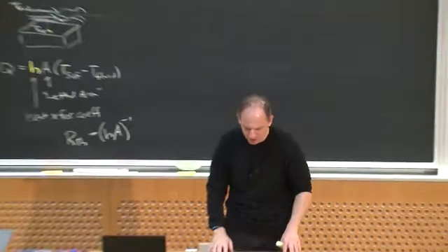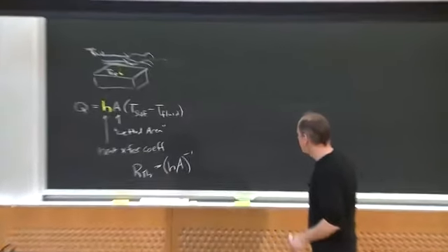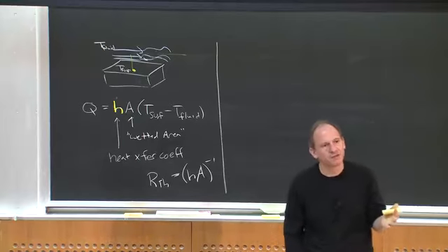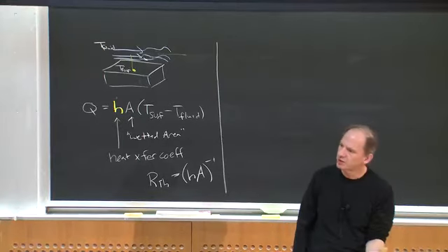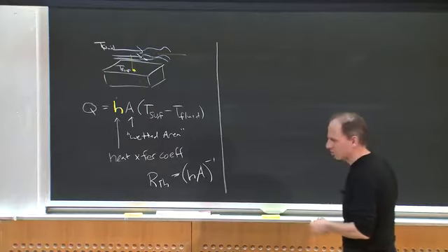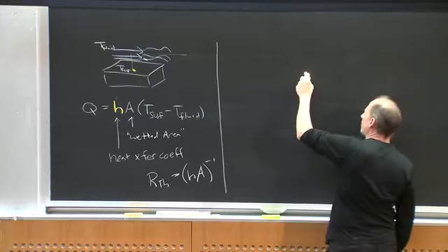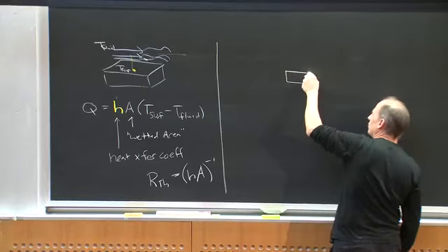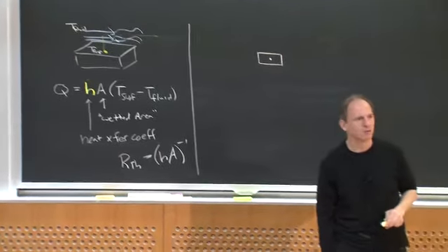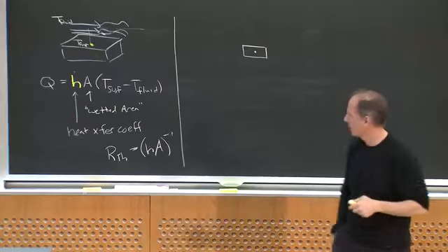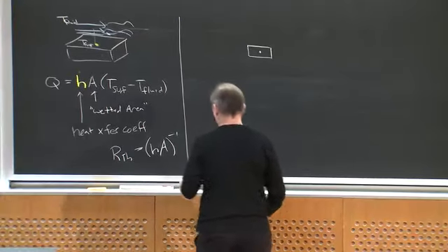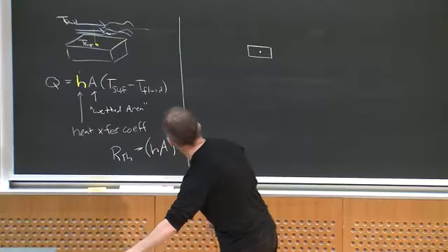So how might we use this? Well, in the typical case, I'm going to dissipate some power in my device. I've got to connect that device through some heat transfer means, and the heat transfer is going to carry it away. So here's a typical structure. Maybe I have some power device. This could be a MOSFET. Basically, somewhere inside this device, I'm dissipating a bunch of power. So that's a source of heat. And then I need to connect that down onto a heat sink.